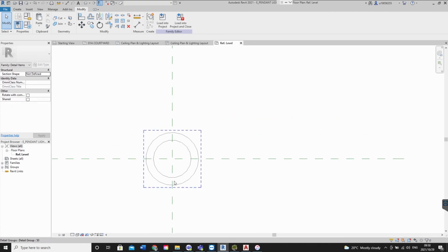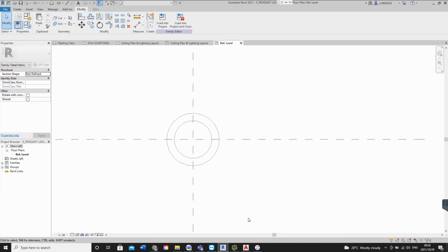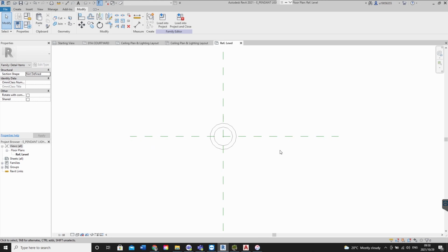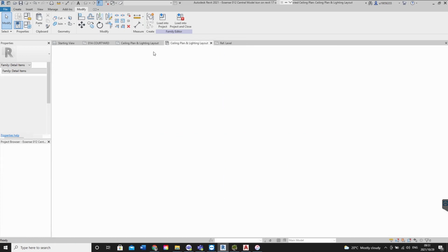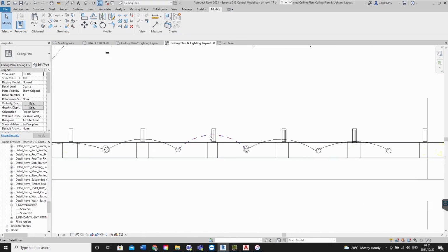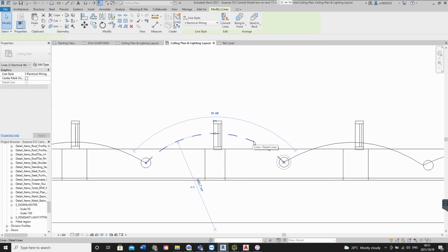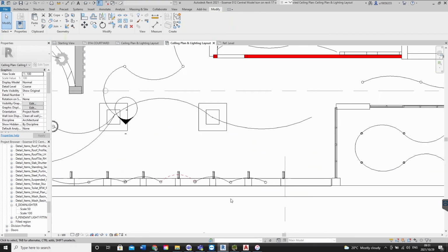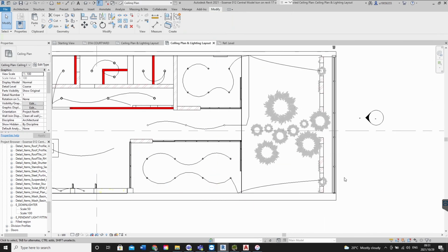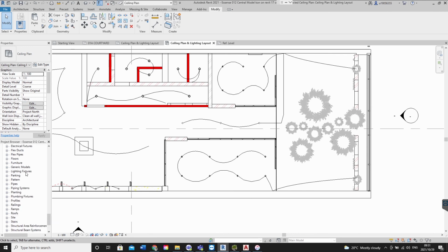So that's pretty straightforward. You just keep making these things as you need the symbols, and then you're done. Then for the rest of your Revit life, you've got these symbols done, made. They work how you know they should work. And it's all drafting. You're technically drafting this stuff. Then you make a legend, and you put all of these in. So while you're dropping in these symbols, start making your legend at the same time.